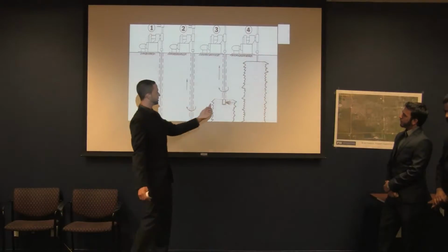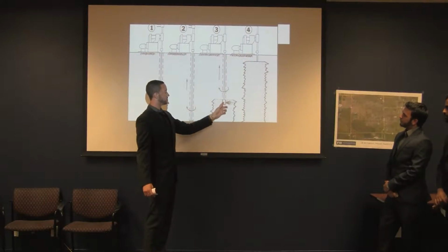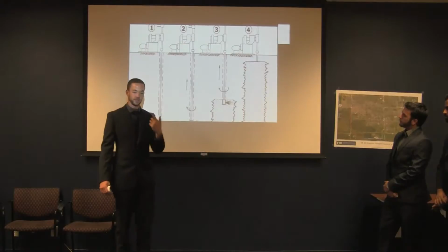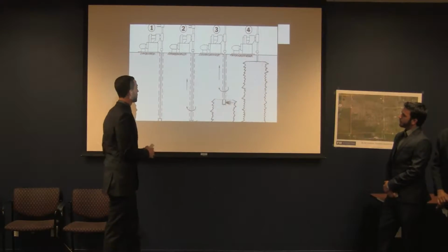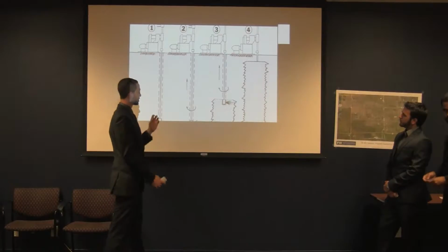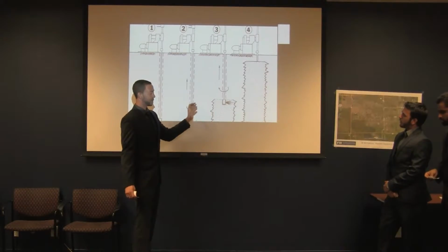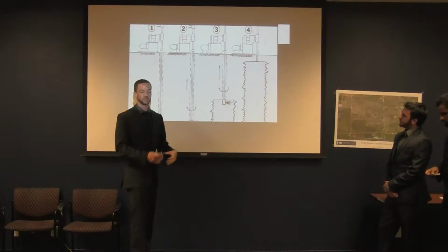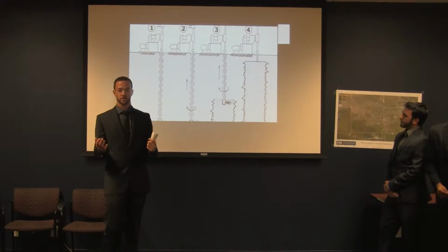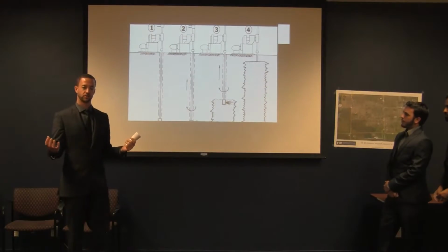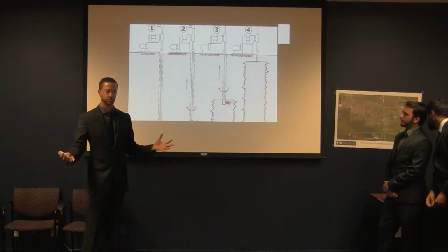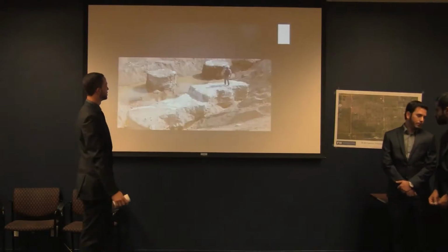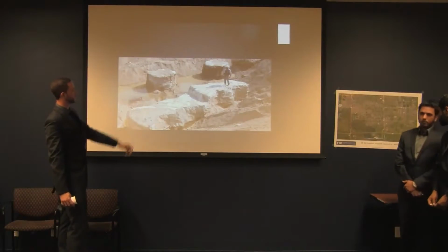And then this is the drill bit actually, and then it spins, it rotates around at relatively high RPMs, and it sprays grout into the limestone. And because limestone is such a porous material, the grout is allowed to infiltrate inside the pores, and that's how you get your strength. Next slide. And then that's how we look after it.